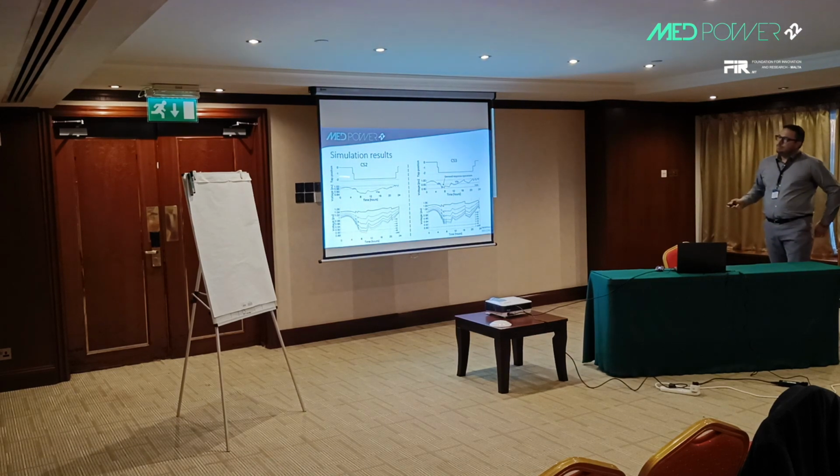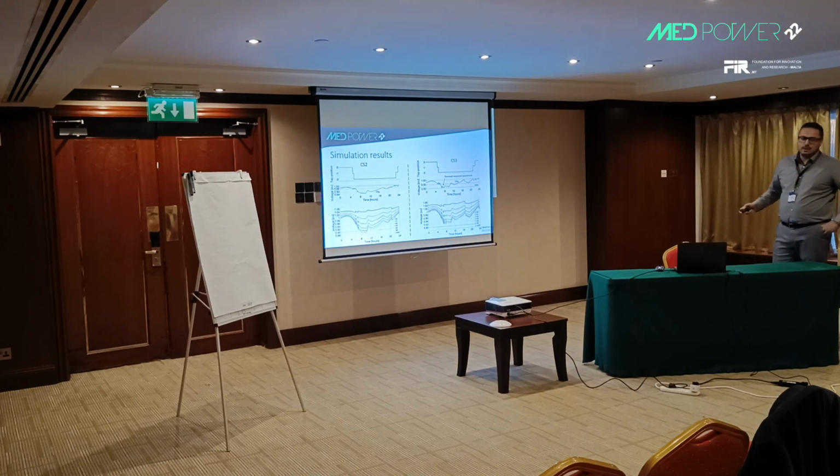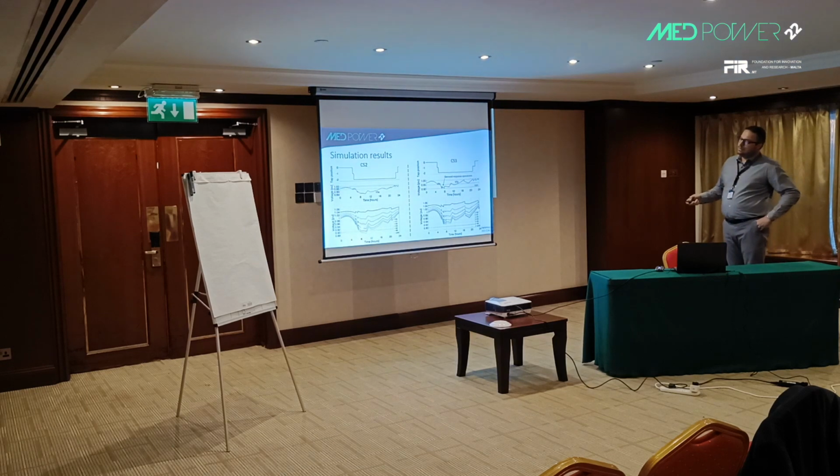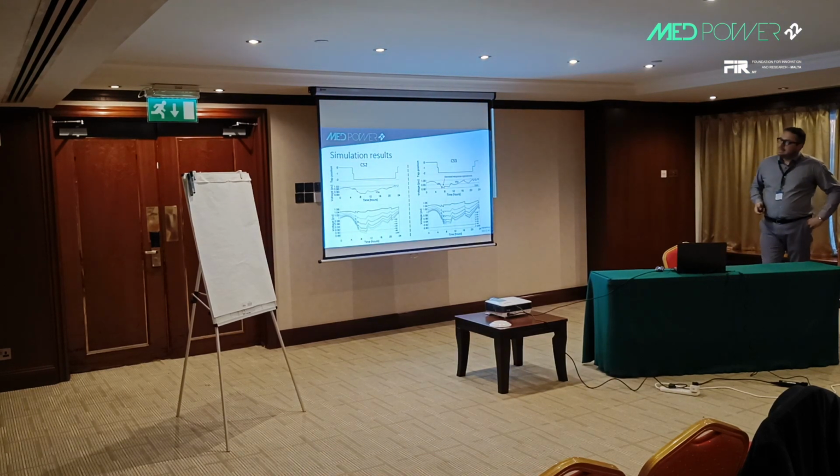In case study 2, the medium voltage, low voltage transformers are also left to regulate the voltage. This measure alone is not sufficient to restore the voltages within the permissible limits, but of course the voltage profile is improved.